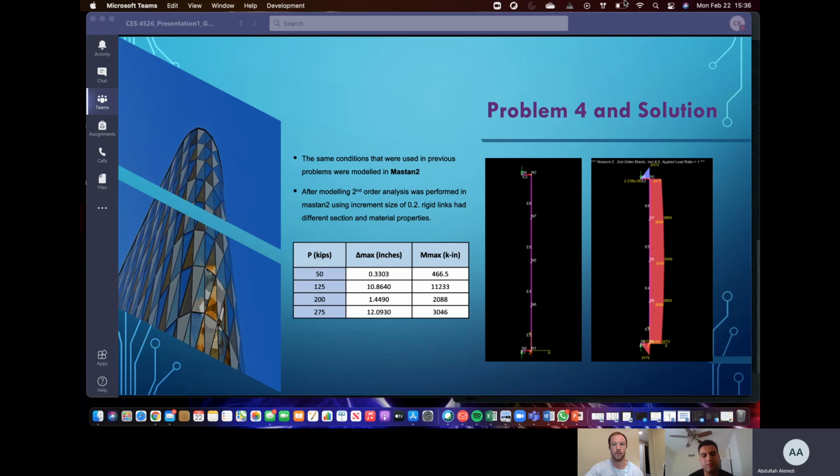The supports of the beam column are assigned by using condition fixities. The nodes in the beam column are selected and the desired degrees of freedom for the nodes are restrained. Loads are defined in the same manner: the nodes are selected and the required load is assigned. Sixth, performing second order analysis.